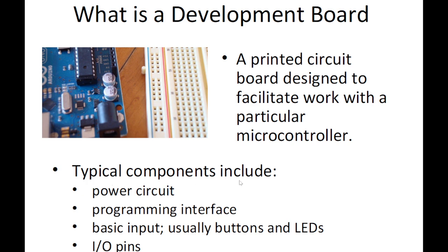The typical components included on a PCB: it has a power circuit, which brings power onto the PCB and powers up the respective components or our circuitry or design. It has a programming interface, and for Arduino it's a USB cable we will use in our lab time to connect the Arduino with the PC or laptop and program the ATmega microcontroller.